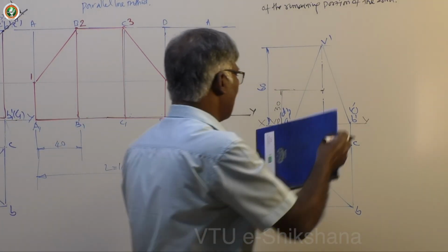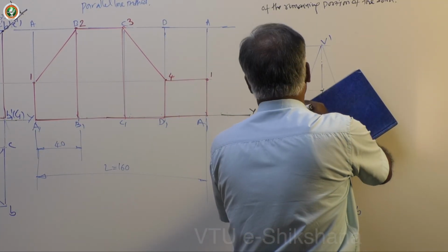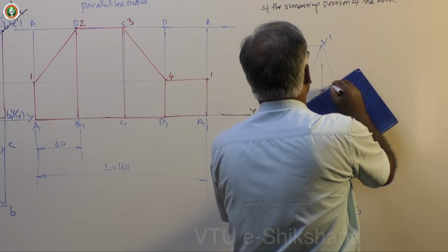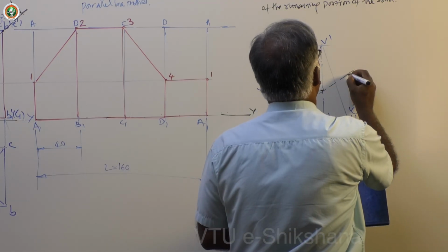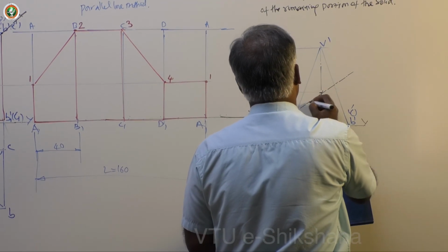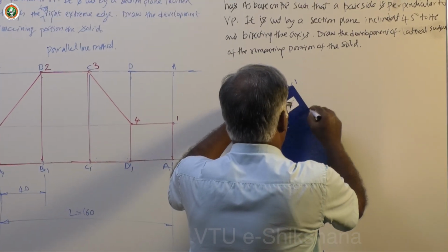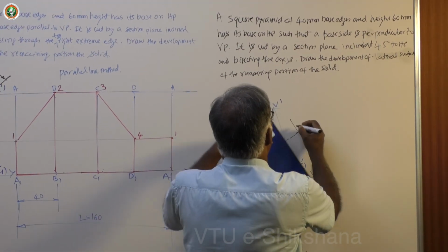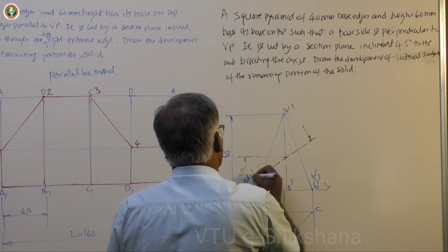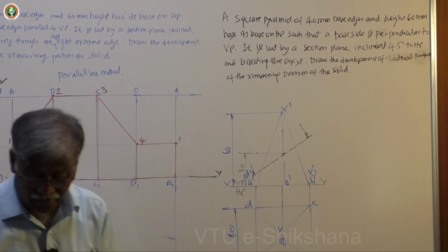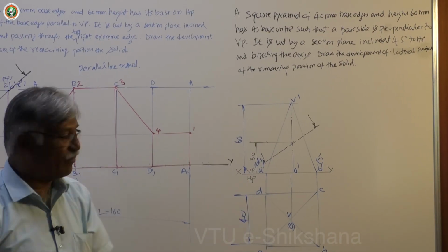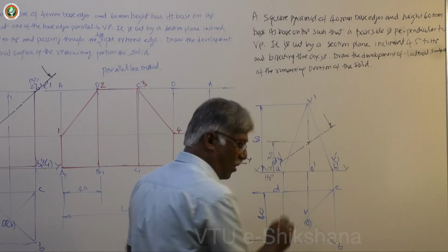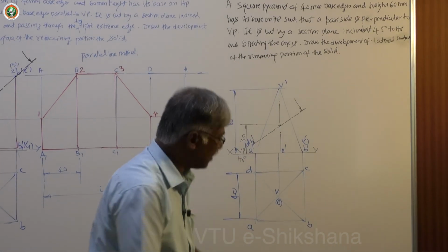So if you draw the 45 degree line, you fix it anywhere, then draw it. Again, full line hyphen, that is the convention for the section plane, and at the end dark a little bit and then put arrows. Then, before naming the intersection points, you dark the portion which is retained after taking the section.